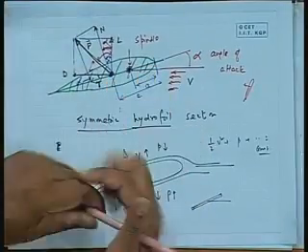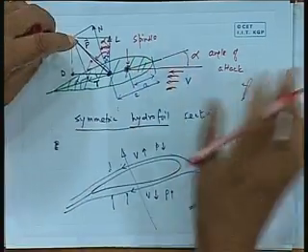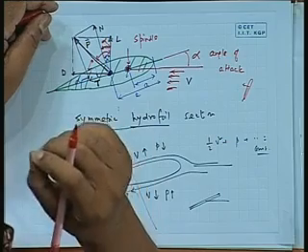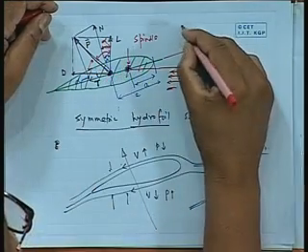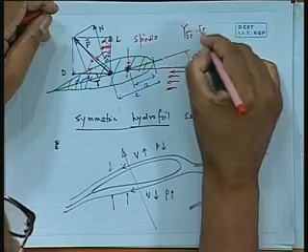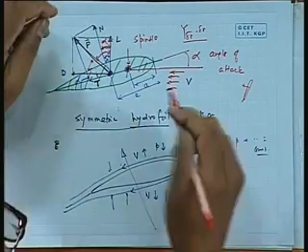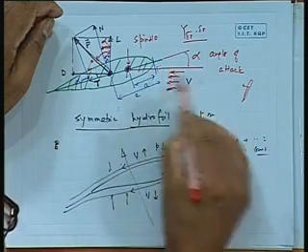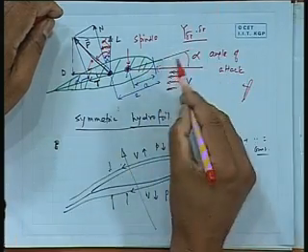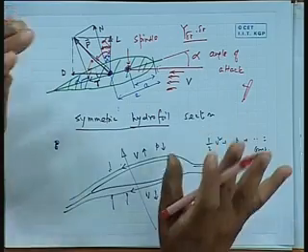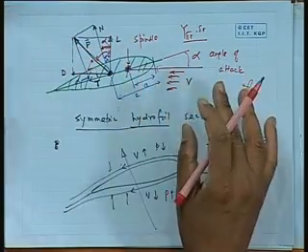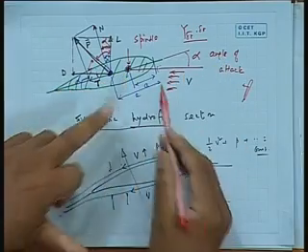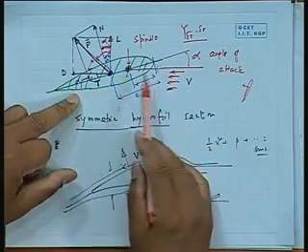It's all getting confusing. What I wanted to say is, see, separately again what we have done. We express the rudder forces in terms of Y delta R into delta R. If the ship is going in a straight line and you have turned the rudder, then alpha becomes the rudder angle, approximately. In reality it may be more complicated than this, but approximately alpha is the rudder angle.